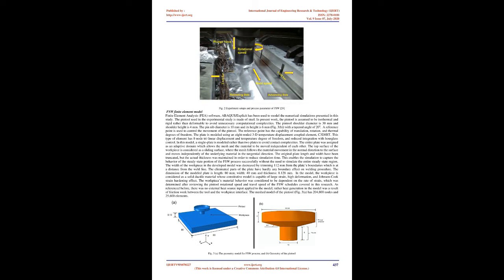First, to develop a thermomechanical model using the Coulomb and the modified Coulomb models to estimate the heat generation during FSW, and to compare the temperature profiles from all the four models with the FSW experimental schedule of aluminum AA2219 alloy to demonstrate the validity of these models.